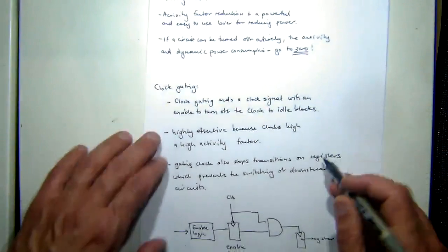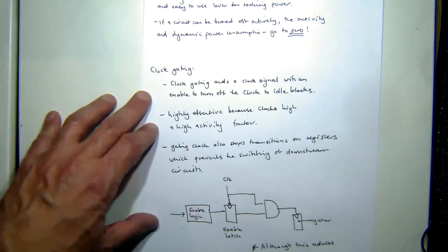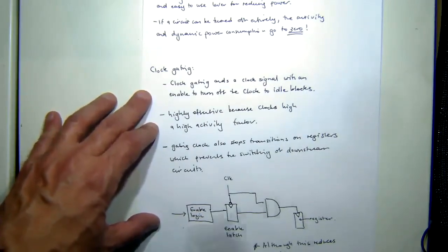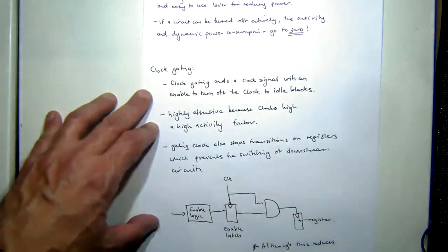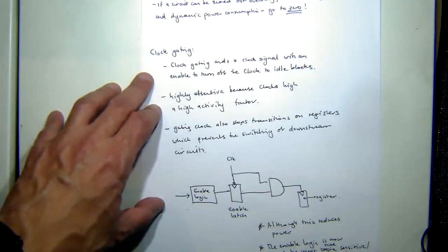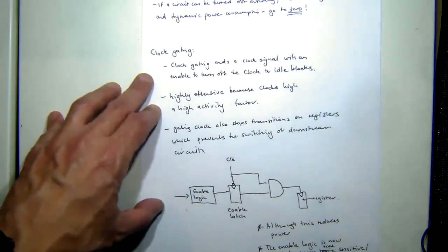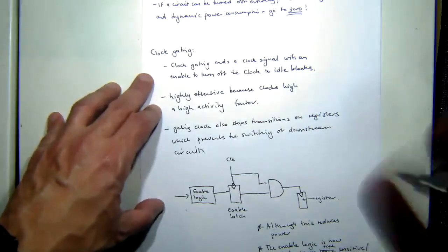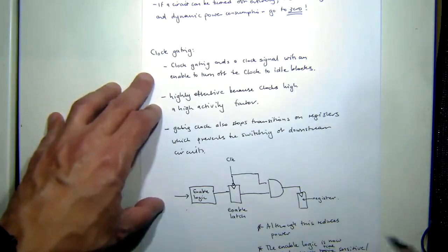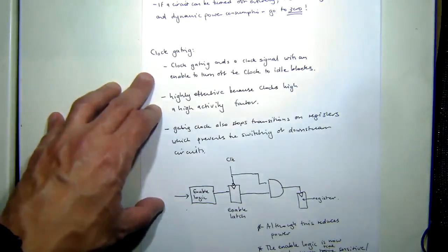What's one way of doing this? And that is clock gating, which, as your colleagues pointed out, is where you write to a register and it switches down the clocks, or certain clocks, in the processor. It's a very common technique that people use these days. So if one of the cores on your processor isn't doing anything, usually you reduce the clock speed to it, so it consumes a lot less power. But that has a disadvantage: when it first starts up, it takes a little bit of time.